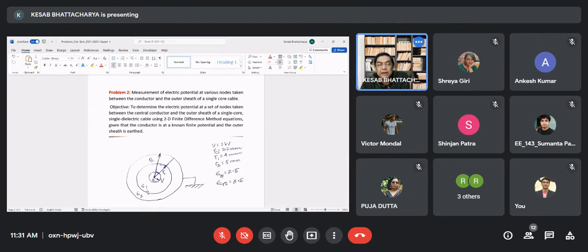So here, what all you have to do, you don't have to consider the entire cross section. Instead, you consider a thin triangular strip like this, right? Therefore, if the strip is thin, then the two external boundaries, one lying on the conductor surface and one lying on the outer dielectric, for them, though these two boundaries are really practically curved surfaces, but for all practical purpose, if the cross-sectional area which we have considered is thin enough, then we can approximate these two external boundaries by straight lines.